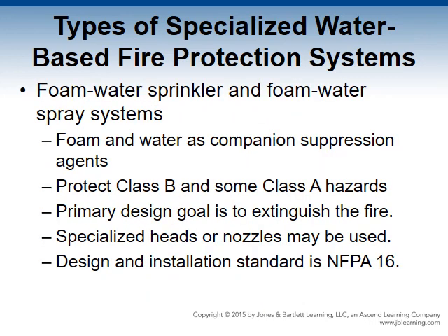Foam water sprinkler and foam water spray systems. These systems use foam and water as companion suppression agents, with the foam water solution used as the primary agent and the water used as a secondary agent. When the foam supply is depleted, the water supply continues until it is shut off. These protect basically your Class B flammable and combustible liquid hazards and certain Class A hazards as well. The primary design goal is to extinguish the fire, but they are also appropriate for prevention, control, and exposure protections.